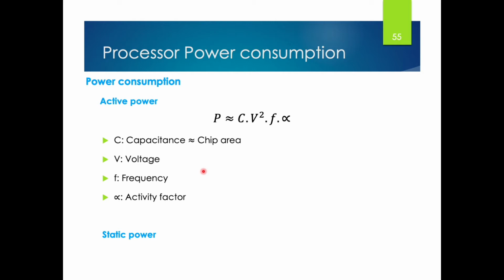When the chip or the processor works, it will consume an amount of supplied power. This power is the sum of two constituents, the static and the active power. The static power consumption, or leakage power, is caused by leakage currents that are present in any active circuit, independently of clock rates and usage scenarios.